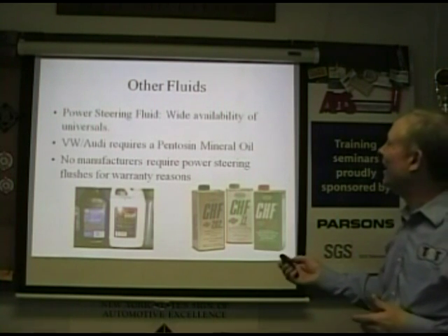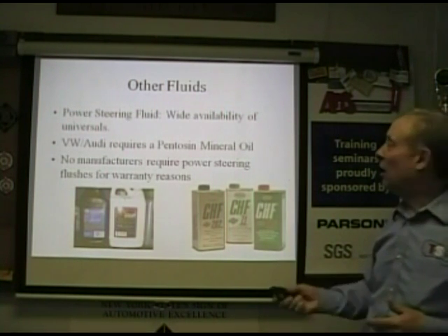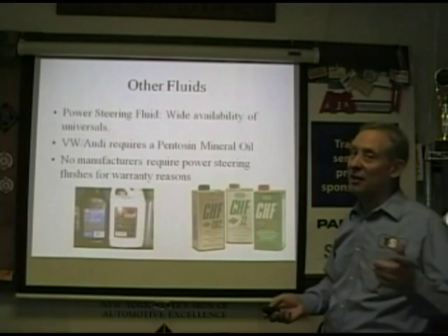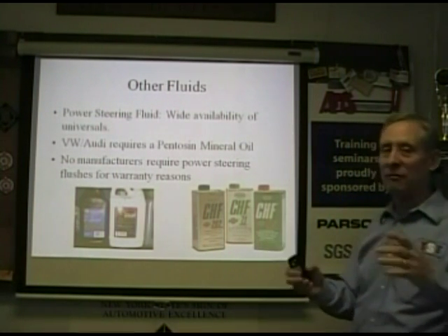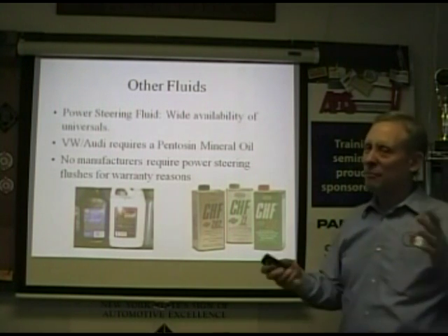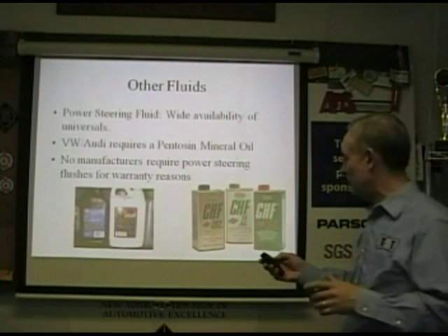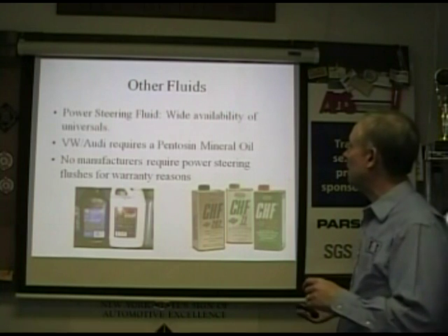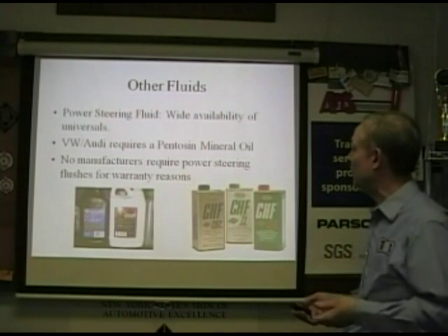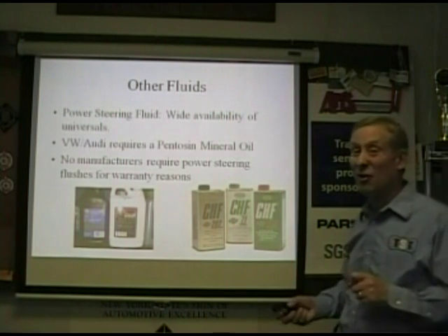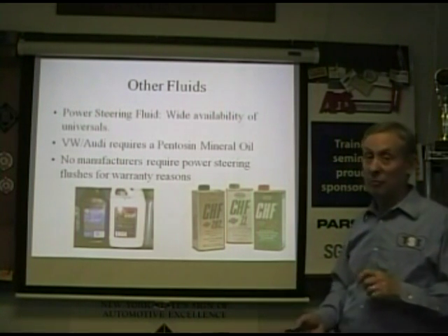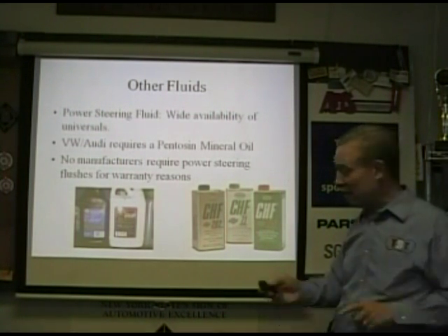Other fluids. Power steering fluid. Wide availability of universals. Again, be careful on this. This is not really part of the regular discussion here, but I like OE fluids whenever possible, and if not, you're kind of a test pilot. I do test pilot occasionally, but be aware of that. VW Audi requires Pentosin mineral oil. You got to read the cap or read the spec on this.